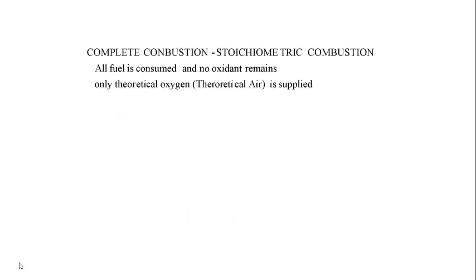Next thing, I want to define something called stoichiometric combustion. Stoichiometric combustion is just a term used to mean that you have just enough air in the reactant side in order to burn all the fuel. All fuel is consumed and no oxygen remains at the product side.